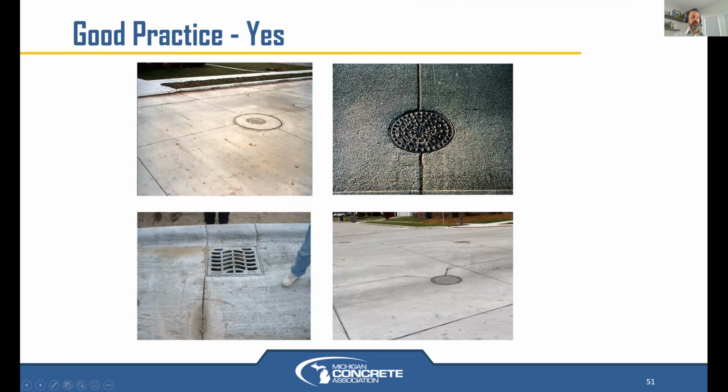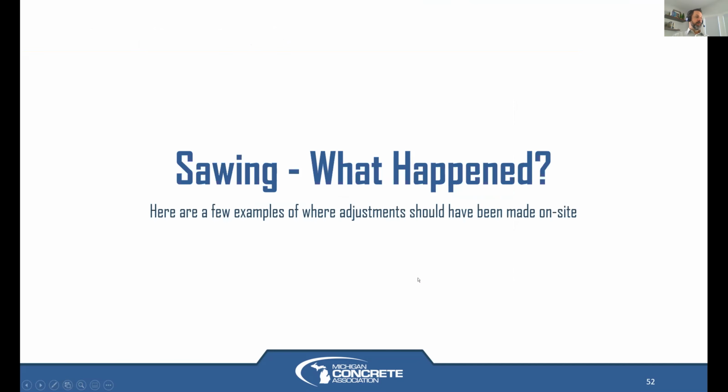I've seen this for some asphalt roads around different agencies around the state that they want to protect their castings with a box out. But we haven't seen this in concrete as much in Michigan recently. Fairly common in Michigan is simply to joint the concrete through an inner line intersecting with the structure. Both longitudinal and transverse if possible, but if at least one, if not the other. We also do want to see a joint coming off of one of the 2 corners of the castings, because we know that is an area where we will see cracking as well.